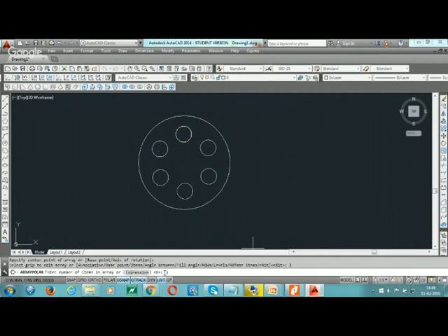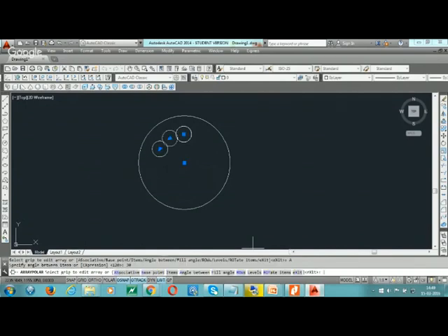We go to the 3, then select the angle between, that is 30, or total fill angle. Here if total fill angle is 360, then it again changes. Now the spacing has changed. This is the placement. It's a number of items and angle between two items, and fill angle. Fill angle is the whole angle.